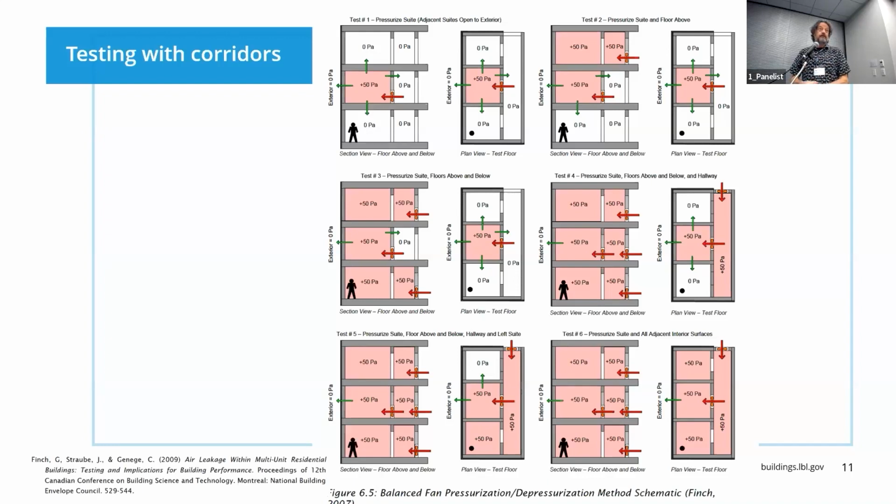For example, this ceiling is not really the ceiling that you see. If we pop one of these tiles off, you'd see a big open space. It's full of ducts that connect this space to that space. And those interconnections that you can't see that connect places together, we find surprisingly often, even in residential cases. And so even though you think you've pressurized all the units that your unit is connected to, maybe you haven't, and I've certainly had that experience.